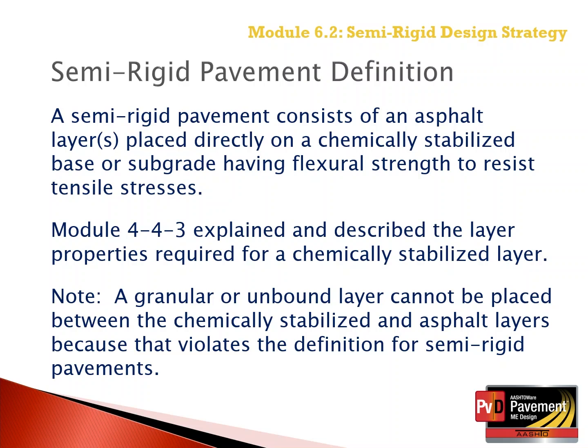So if a user does have a situation, for example, where the subgrade has been stabilized with soil cement, and that stabilized soil cement has flexural strength and can resist tensile stresses, and then a granular material is going to be placed between the soil cement and asphalt layers, that would, in terms of the MEPDG, be defined as a flexible pavement, and the soil cement would be simulated as a high representative modulus.